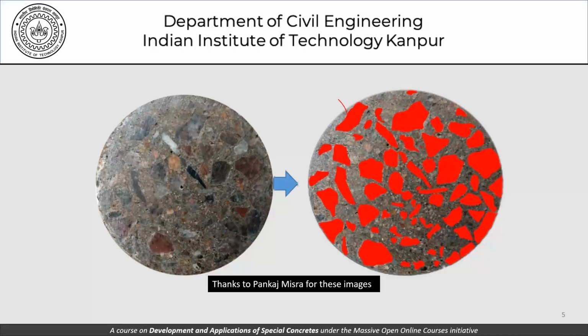Those of you who have probably read some books on concrete engineering would remember that what we say in those books sometimes is that the mortar should be able to coat the surface of coarse aggregates, and the paste by that token should be able to coat the surface of sand and so on. I think we'll not get into that so much, but yes, that is the principle and that is what governs our thought process, that the coarse aggregates are suspended in mortar.